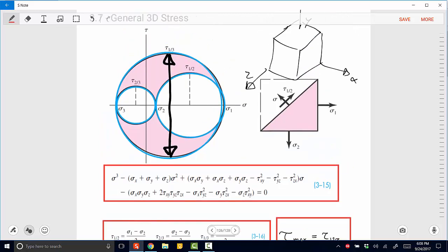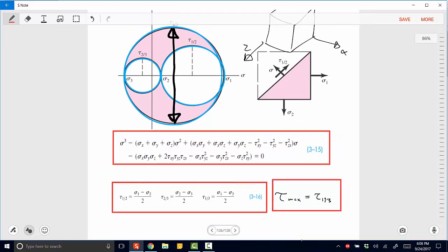So it's going to represent that actual outer Mohr's circle that encompasses all of the stress within our body. So when we're dealing with 3D problems, Mohr's circle is very challenging. There are 3 circles that we need to generate here to really understand behavior.